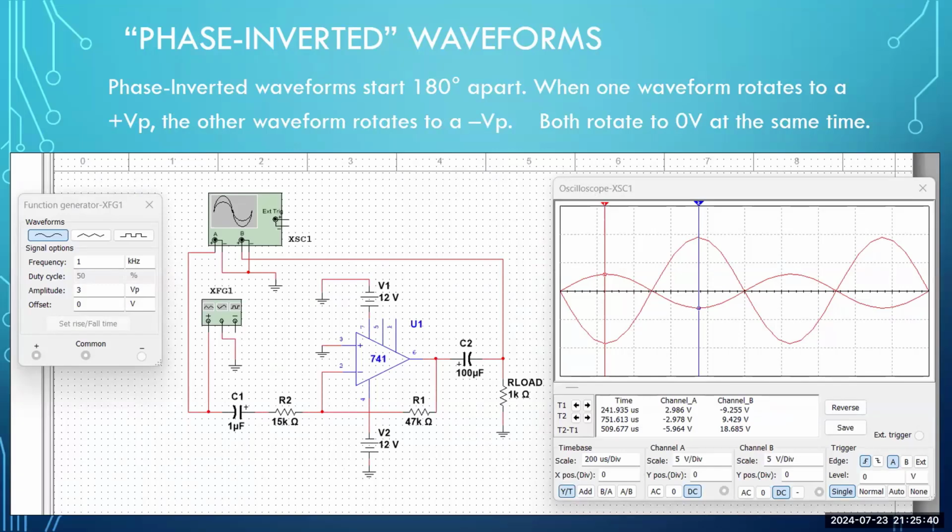So if you look at channel A of the oscope, the green box above it, channel A has a red wire that attaches to a node that is also connecting the positive output of the function generator going into the capacitor. And then the signal will go into the circuit. The ground of the function generator is attached to ground. The grounds of the oscope are attached to ground. And as I've said, this is an open loop schematic. We've explained open loop in a previous training video, open loop versus closed loop. This keeps things looking much neater than having all the grounds tied together at one point.